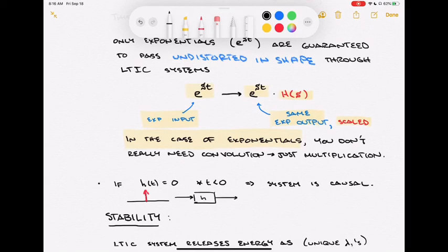And then what comes out? Well, we know what comes out is the unit impulse response, and maybe it looks something like that. Maybe it looks like some sort of kind of wonky curve like that. So we had delta in and we had h coming out. When is the first time that the input is non-zero? Well, it's first non-zero at 0. If the system is causal, if it can't respond to future inputs, it can't respond to that delta function until 0 and later.